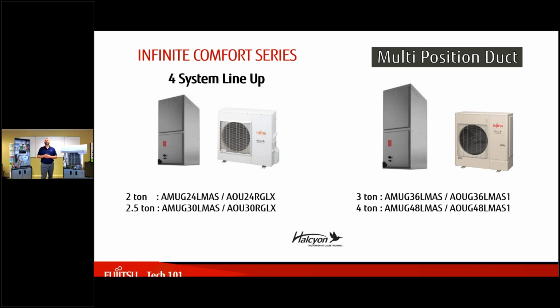New to the Fujitsu lineup here, we have our multi-positional air handlers. These are something that I'm very excited about. It kind of brings the unitary to the Fujitsu world. We have these available in 2, 2.5, 3-ton, and 4-ton setups. As of right now, they are 1-to-1, only single zone applications. We're hoping that we start to move towards maybe adding the 2 and the 2.5 towards a multi-zone system at some point in time. But right now, they are going to be single zone systems.